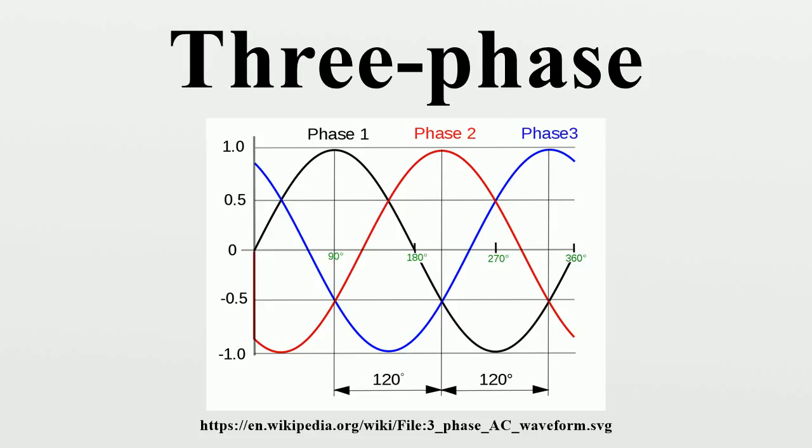The field produced by a single-phase winding can provide energy to a motor already rotating, but without auxiliary mechanisms the motor will not accelerate from a stop when energized. A rotating magnetic field of steady amplitude requires that all three-phase currents be equal in magnitude, and accurately displaced one-third of a cycle in phase. Unbalanced operation results in undesirable effects on motors and generators.